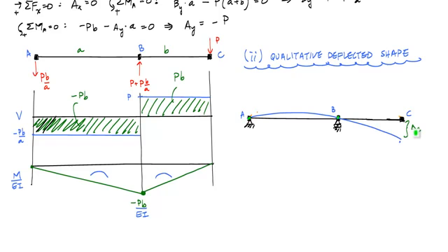One thing to look at is the tangent line at point A. Let me draw this tangent line. There's my tangent line at A. What I notice is that this distance, from this point to this point, is defined as the distance to point C from the tangent line at A. Using the second moment area theorem, I could calculate this, but that's not what I need. I need this delta C, the magnitude of displacement of point C.